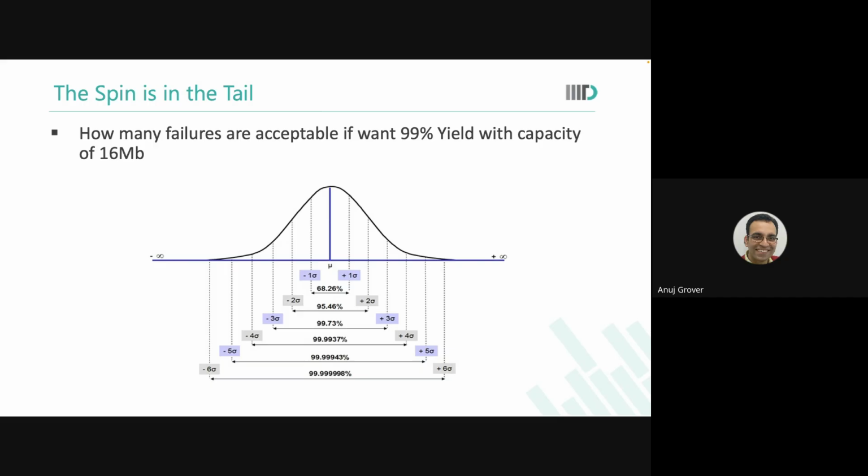When you work on your projects, many of you will be designing memory cells or doing sense amplifier design or something like this. Just play with the number of Monte Carlo simulations, and you will see that the mean stabilizes within the first 50 simulations itself. Whether you run 50, 100, or 1000 simulations, the mean will be practically within 1-2% of the value from a very large number of simulations.